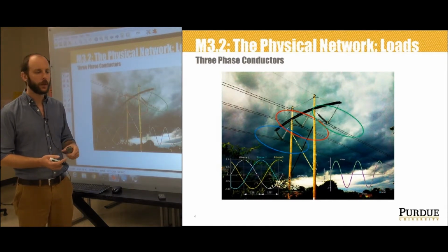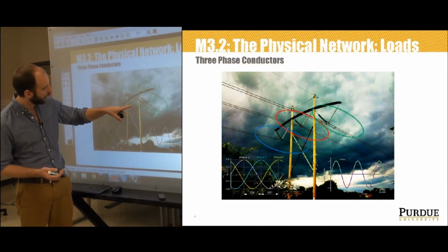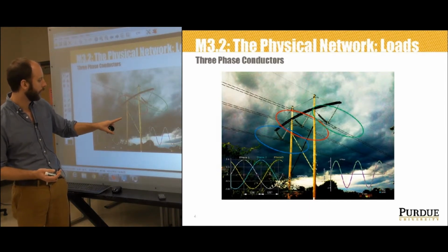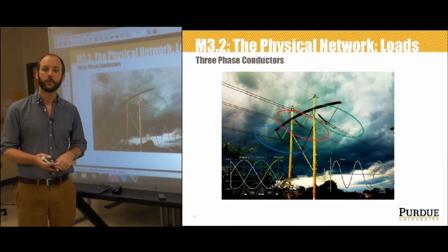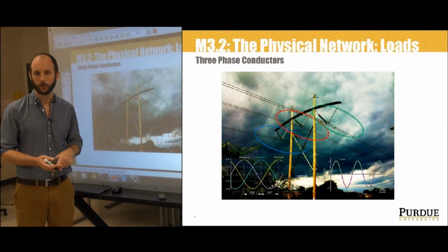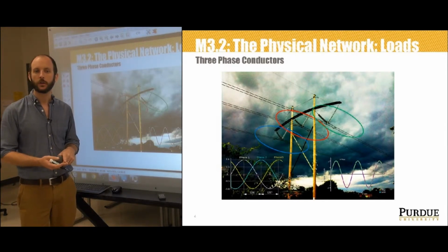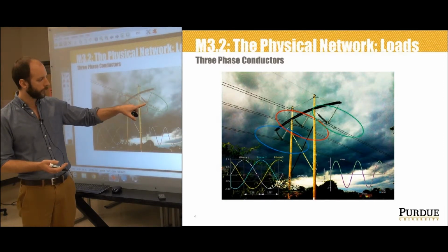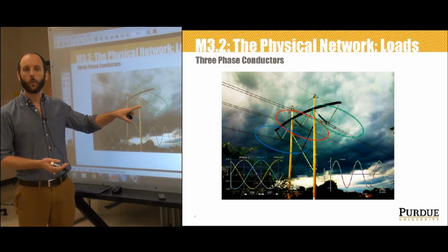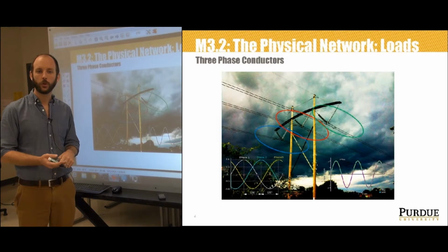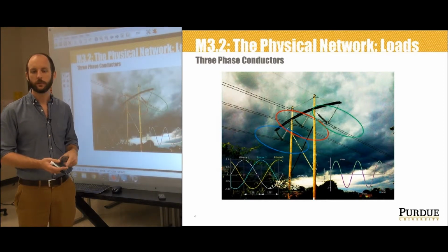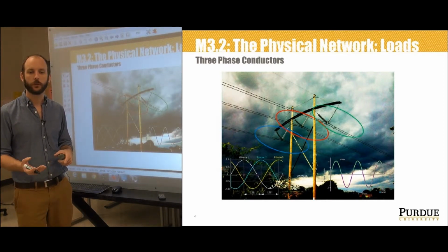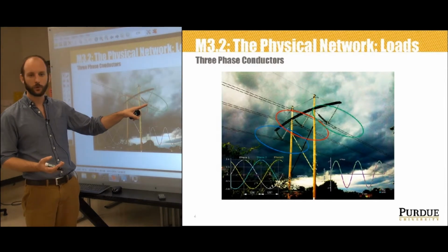And you'll notice that there is a spacing between these two lines, these two lines, and these two lines. And the spacing of those three phases is chosen based on the voltage level. Higher voltages are going to need larger spacing to reduce the possibility of electrical arcing, whereas if we look at a single phase, wires of the same phase can be co-located on these same insulators since their voltage difference is zero, right? These are at the same voltage.